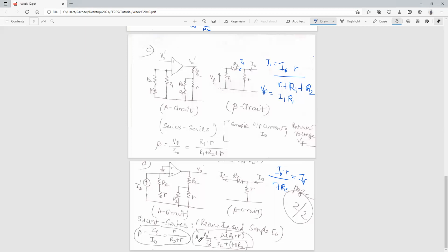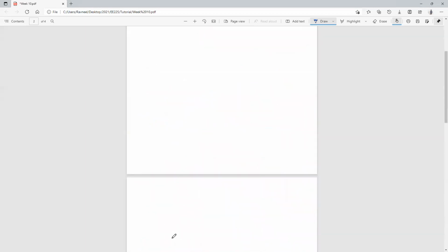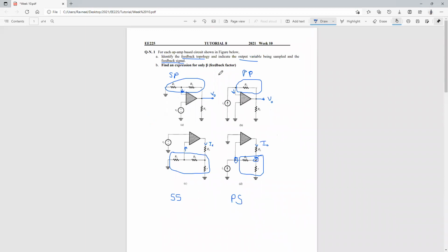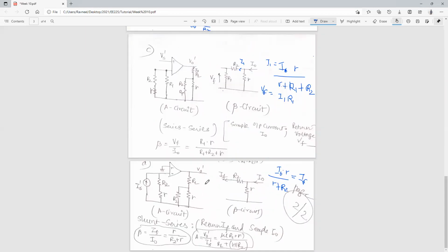Remember, like I said, the open loop gain can be written in multiple factors. However, for this tutorial we are just concerned with the beta factor. So in this case, our feedback gain is equivalent to R upon R2 plus R. You can ignore the alpha variables, as A could be written in multiple variables.